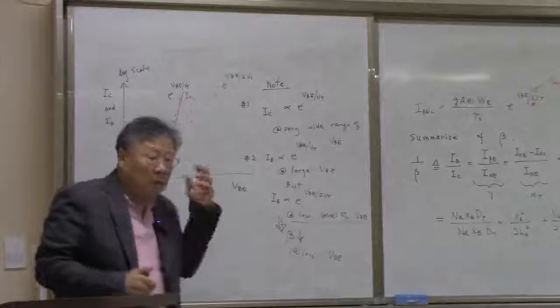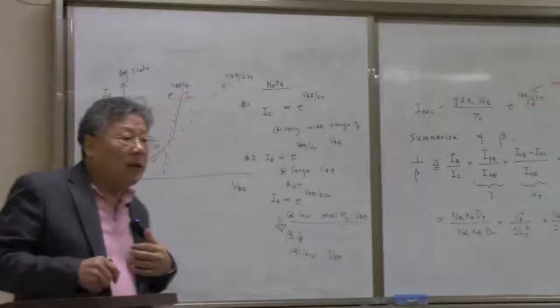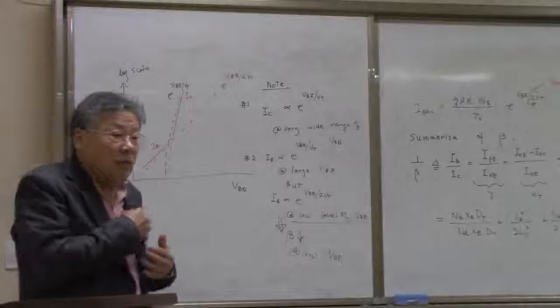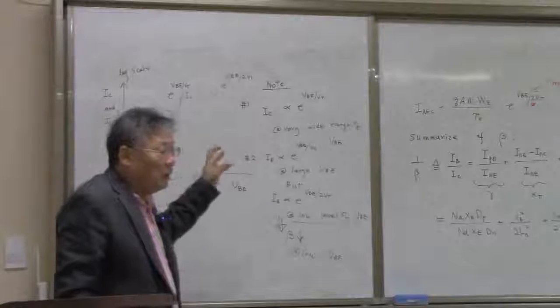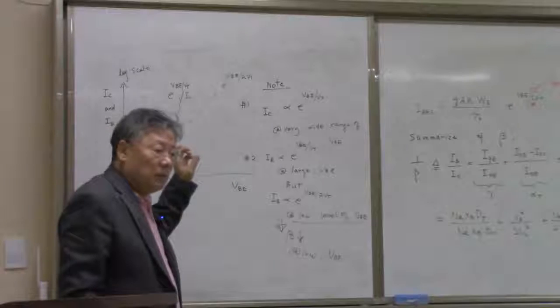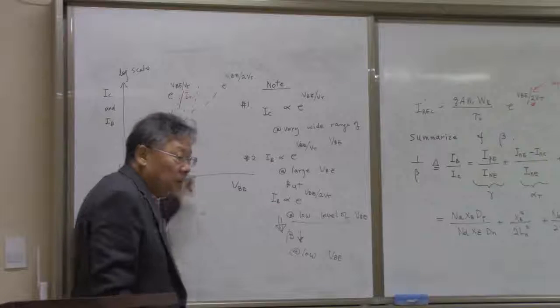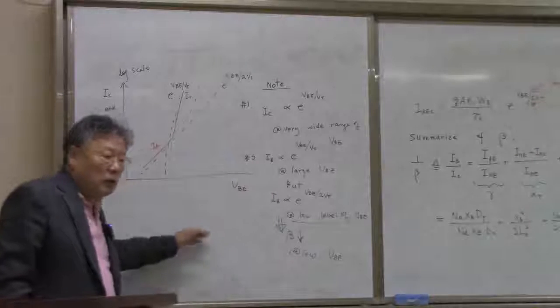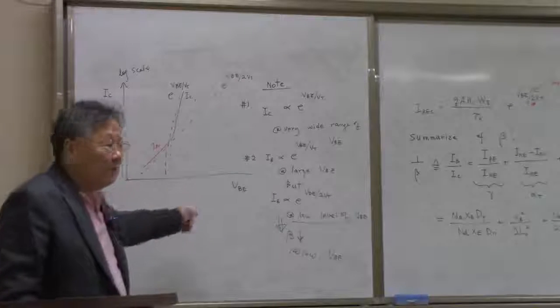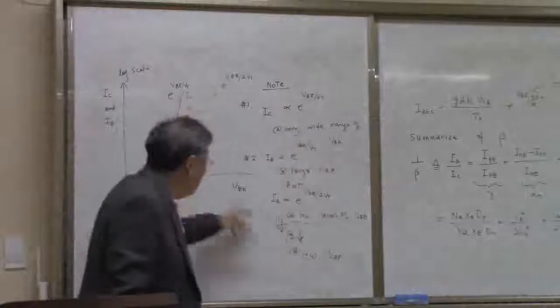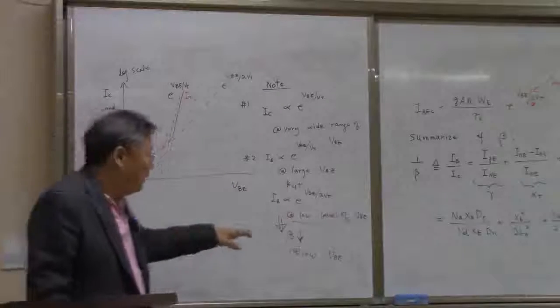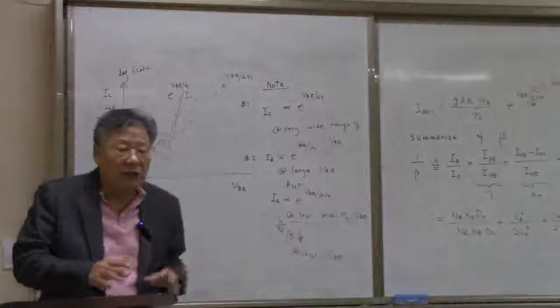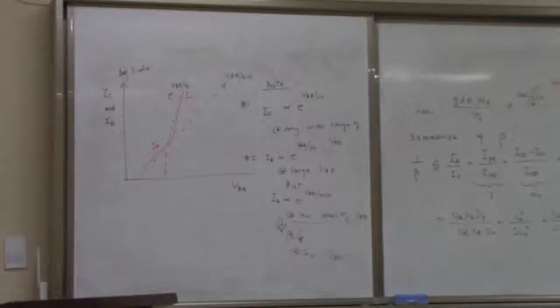So, for example, the hearing aid or the pacemaker, which you have to embed in the heart, those kinds of medical devices have to be made carefully, so that the total gain is not governed by the space charge 2kT values here, because the signals of those special devices are very small. It has to work under the very small signal of the base emitter voltage.